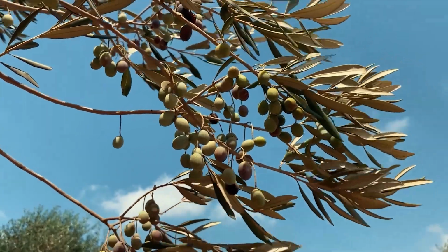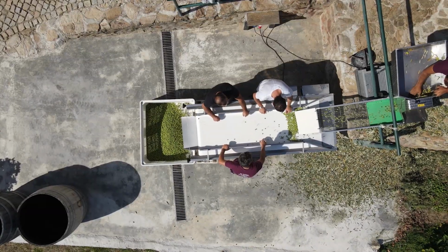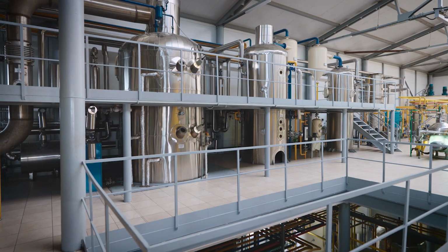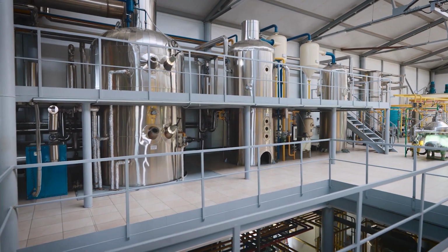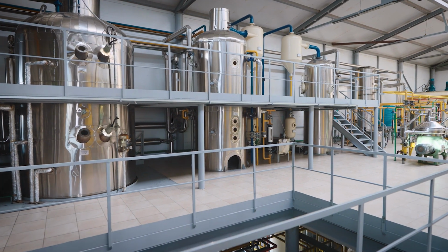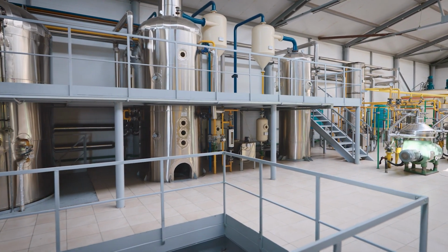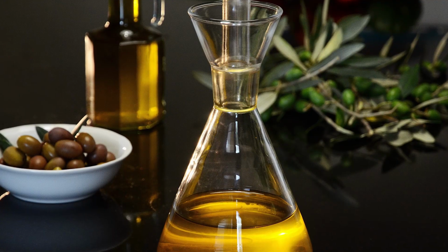Vegetable oil is obtained by first separating it from the part of the plant in which it occurs. This is usually the seeds or the fruits of the plant. It is then ground or crushed. Vegetable oil is obtained by mechanical extraction, pressing, or by chemical extraction using solvents. A more modern technique is also on the rise: extraction with supercritical CO2. The extracted oil can then be purified and, if the intended use so requires, also refined or chemically treated.